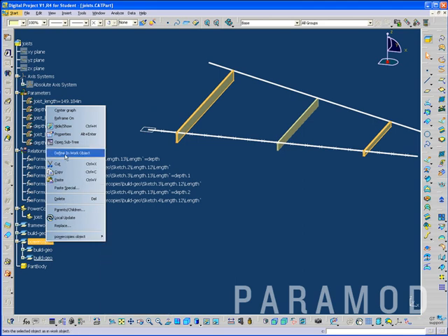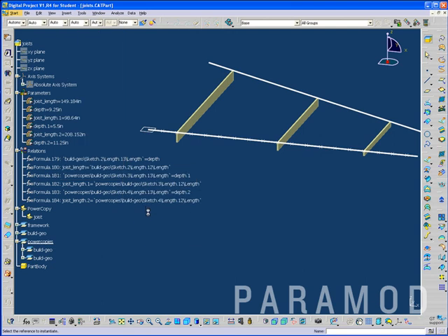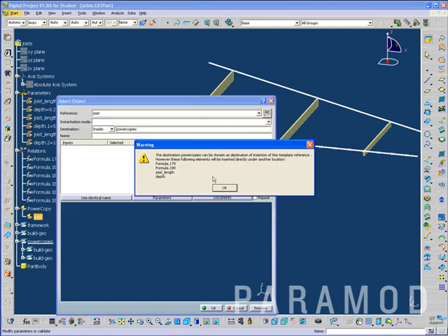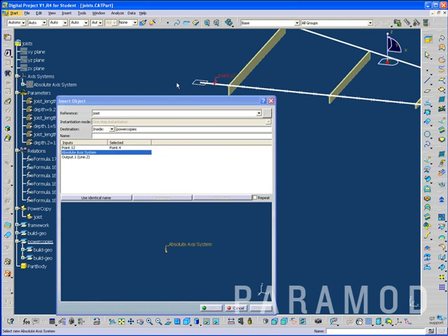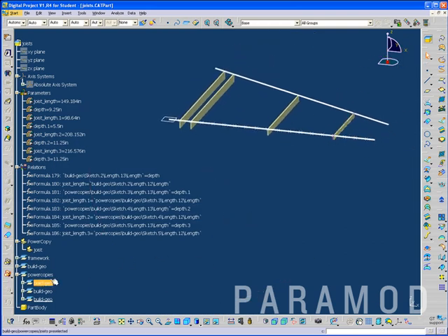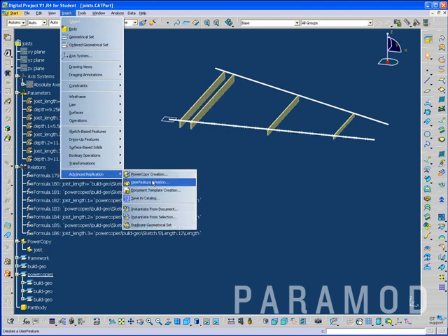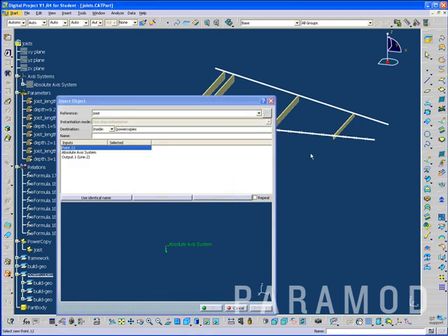And so I might just do this a couple more times. I can make power copies current again. Insert this, select joist, say OK. Select the point, absolute axis, and then the line. Say OK. What I'm trying to do is just get enough within here that I have a sense if this is working the way that we want it to.